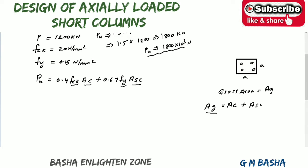Here assume the area of the steel will be equal to 1% of the overall gross cross sectional area. 1 by 100 means 0.01 Ag, so Asc will be equal to 0.01 Ag.